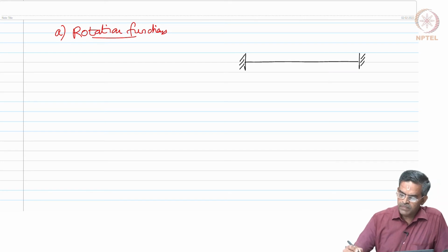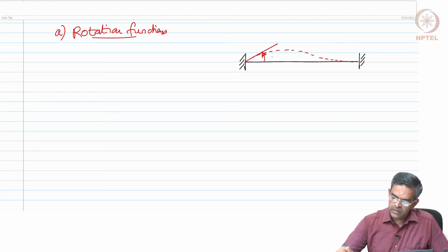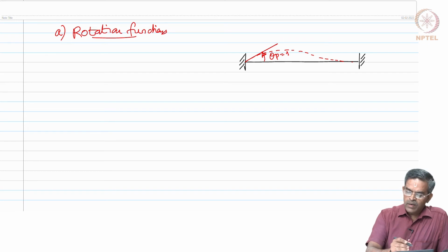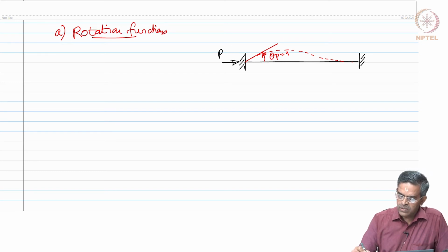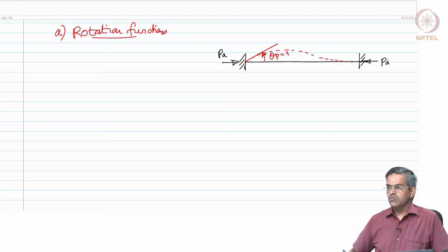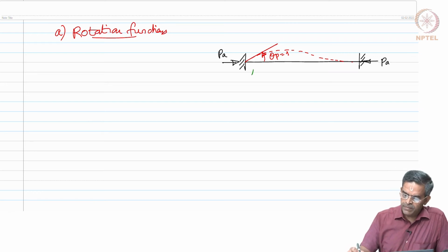The beam is now subjected to a unit rotation theta p. So, it is the same algorithm what we did in the beam earlier. That is why I explained the beam analysis first. Okay. Now, let us mark the axial force present in the section, is it not? This was new. In the earlier beam analysis, this was not there. Let us also mark the degrees of freedom.